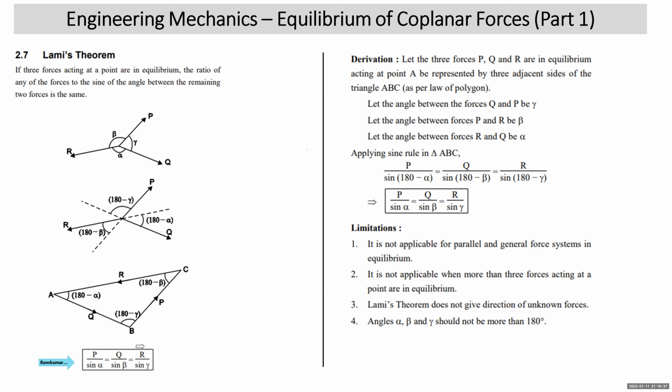I repeat again, Lami's theorem states that if three concurrent forces are in equilibrium, then the ratio of any of the forces to the sine of the angle between the other two is constant. Like this, P upon sine alpha, Q upon sine beta, R upon sine gamma.